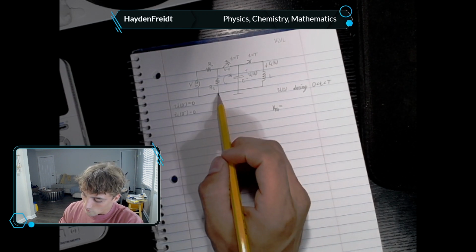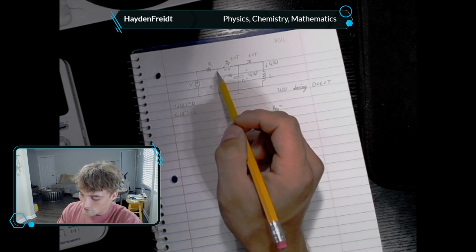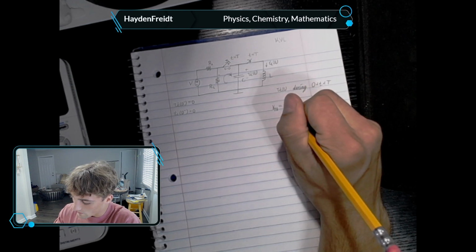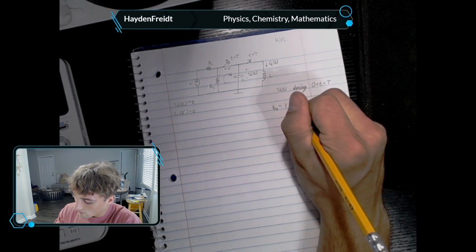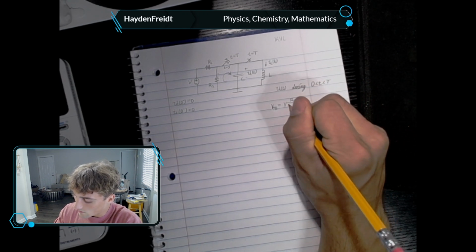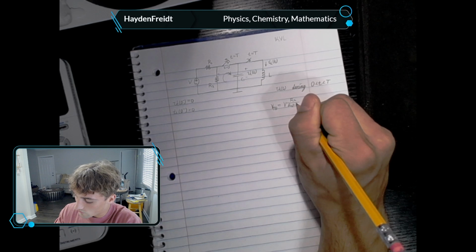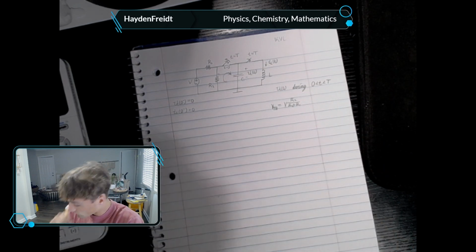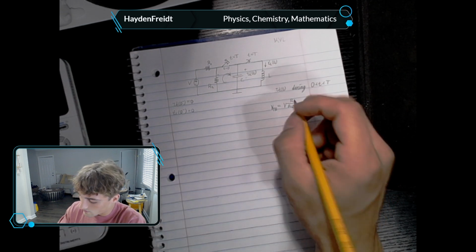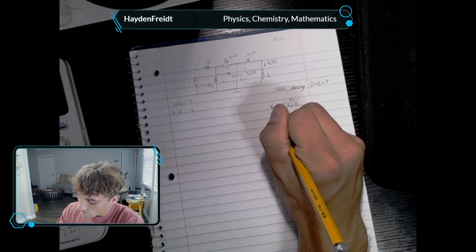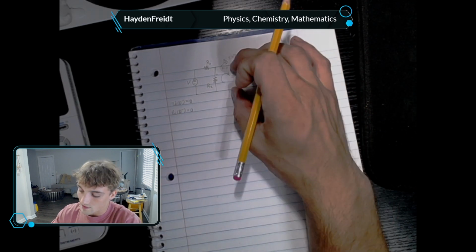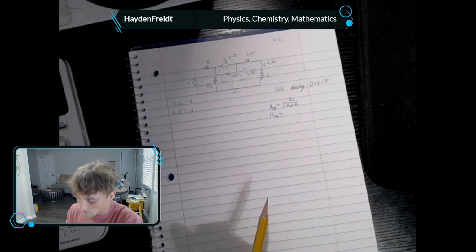Now, in order to define the voltage across this resistor, we're going to use the voltage divider relation. This is simply going to be the input voltage V. Since we're going across R2, R2 is in the numerator, divided by the sum of R2 and R1. So that's our Thevenin equivalent voltage. Now we have to define the Thevenin resistance, R sub TH, which is the resistance perceived by the capacitor itself.